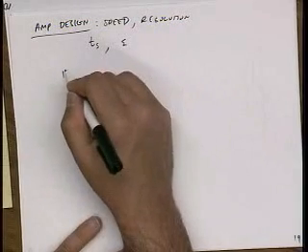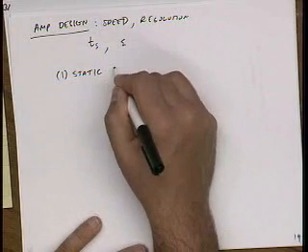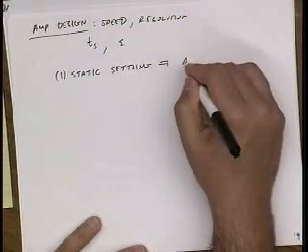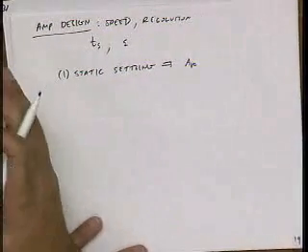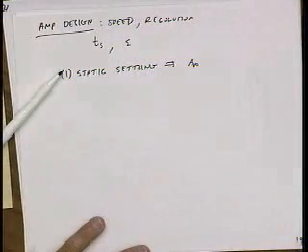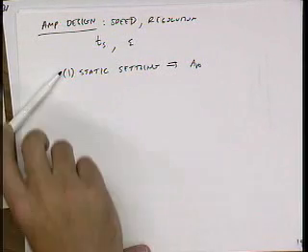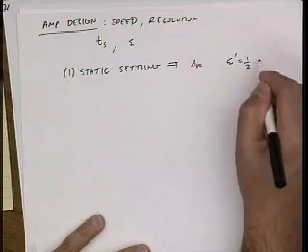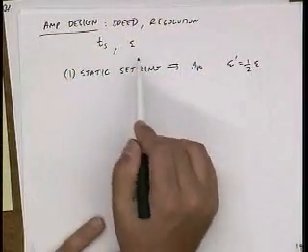Okay? And we've learned in this lecture and last lecture that there's two components. One is the static settling, which is really governed by how much DC gain you have. At the end of the day, it's kind of surprising, but that DC gain matters. Because as your amplifier settles, as you wait long enough, it's really that DC gain which is rejecting your error signal. So usually we have to budget this error into two terms, right?